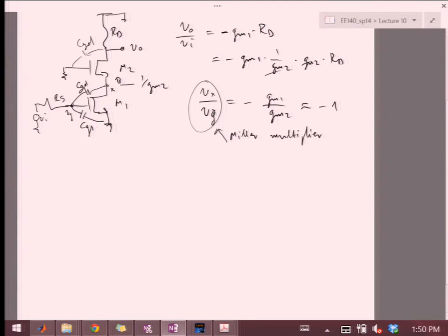So what this means is this first stage doesn't really behave like our common source amplifier in the normal topologies, because its voltage gain is actually very small. It's approximately 1, right? But it's just transducing voltage to current so that this common gate stage can actually do all the amplification, okay? And we know from the common gate analysis at the beginning of the lecture that the common gate amplifier has a lot wider bandwidth. So what I'm doing intuitively here is improving this input bandwidth simply because I'm killing the Miller effect. So my CGD is not as big as if I was basing all the gain of the amplifier on this stage over here, right? So I'm improving the input bandwidth.